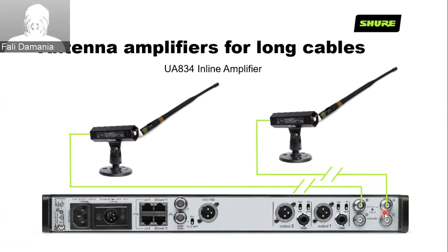And again, just to remember, you will use this amplifier, and the amplifier that's on the fish plate antenna, only to compensate for cable loss. There's absolutely no other area that you will use these amplifiers for. So you go back to that cable loss chart. From there, you select the cable that you're going to use and the distance, you calculate the loss, and then you use the inline amplifier to make up for that loss. But again, keeping in mind that the loss along any one of these paths, so path A or path B, needs to be kept at 3 dB, or worst case scenario, I'd say, under 5.